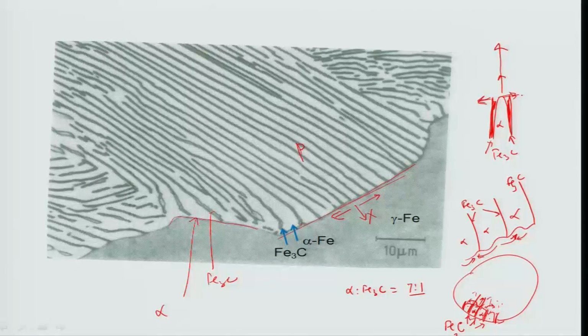So ferrite will give away all the carbon, saying I do not require any carbon, and this carbon will then go to the sinks of carbon, and what are the sinks of carbon? Cementites. Cementite requires carbon, and this happens easily if you have edgewise diffusion, and edgewise diffusion basically solves two problems nicely. One, edgewise diffusion is very fast. Why? Because the diffusion path is very small. From ferrite to the nearest cementite lamella is hardly a couple of nanometers away, or maybe tens of nanometers, or when they are growing, maybe hundreds of nanometers away, not more than that.